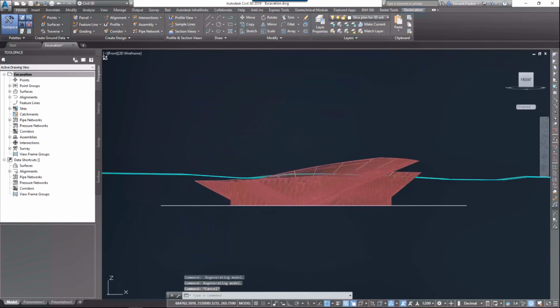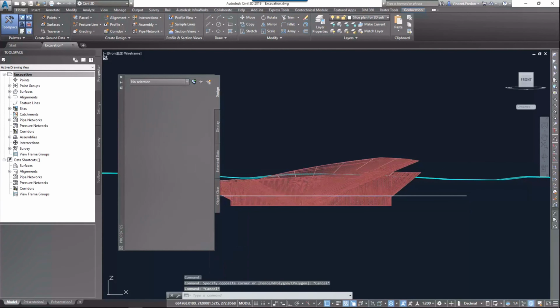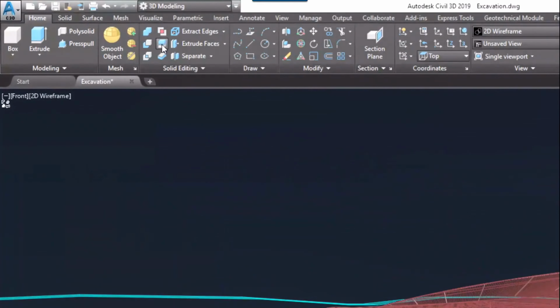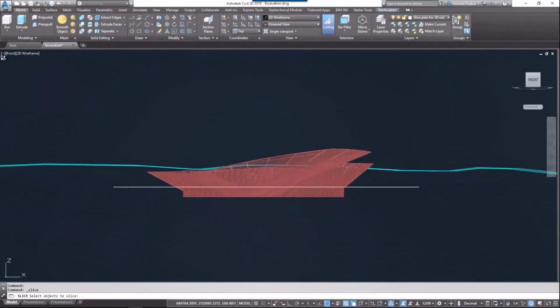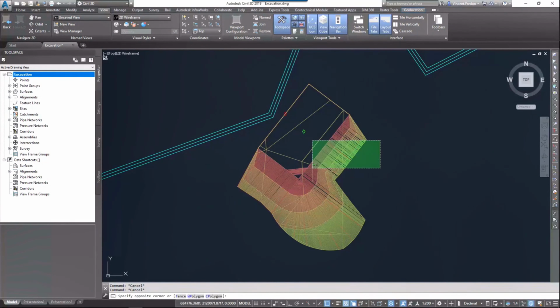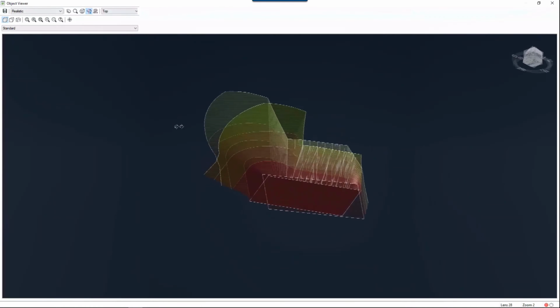For this manipulation, I use a tool you have in AutoCAD. It's basic 3D AutoCAD manipulation. With this tool, you can slice a 3D solid according to a plane. Then I've managed the plane according to different elevations. And for each elevation, I've asked AutoCAD 3D to cut the solids. And I have different slices with this manipulation. I have 4 different 3D solids from the original one.